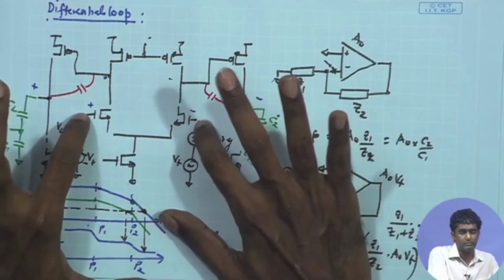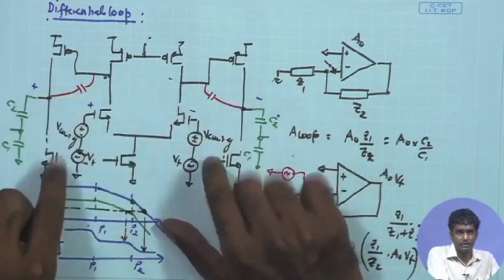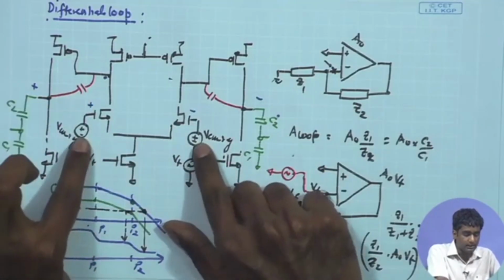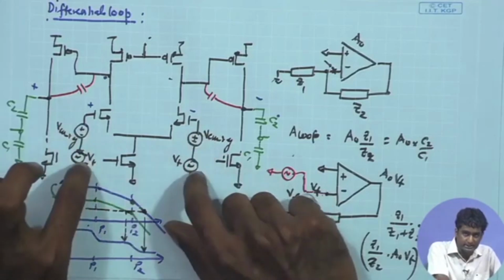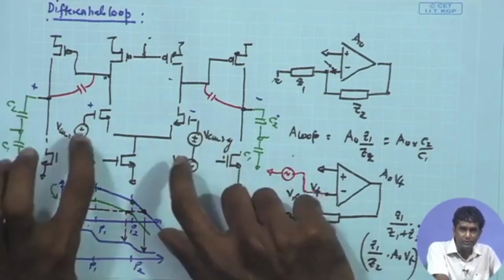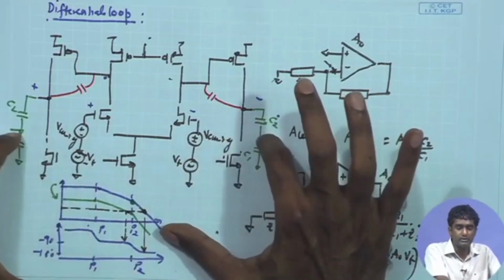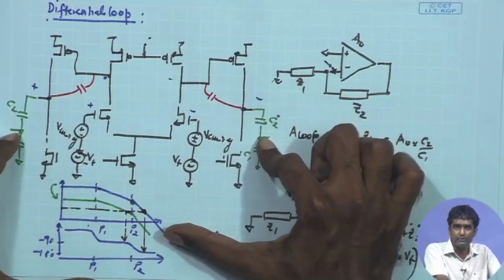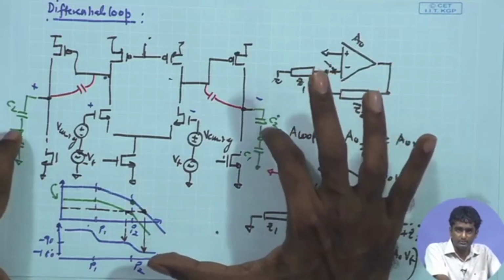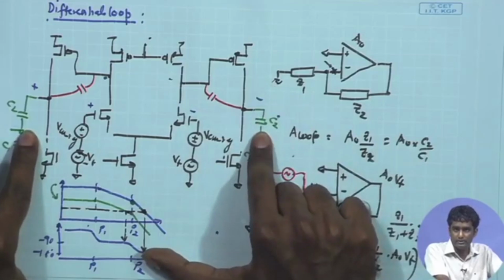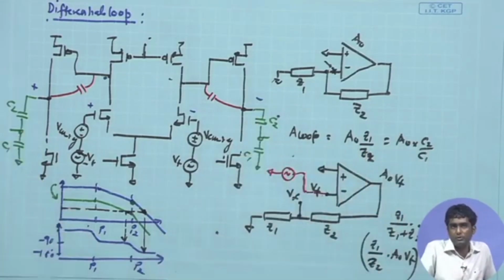So, to be accurate, you can always keep the RF over here, but even in that case you need to make sure that you are using a single source over here with a DC level equal to VCM ref, and then on top of that you are applying the AC signal VT for testing, and then you are obtaining the output signal over here, and then phase response will be given by the gain from this point to the final output at the division of this capacitor. So, this is how you will be looking at the phase response for the differential operation.